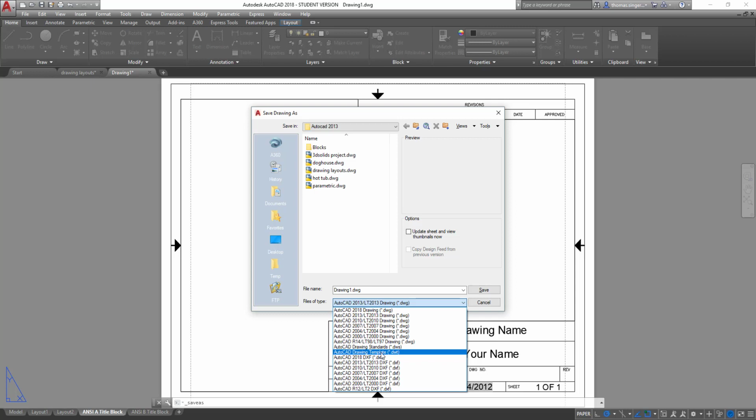So you can create a title block as a template that you can then bring in and apply on top of a layout. That way you're controlling exactly how your title block acts and reacts on the paper. You're not scaling the title block to try to fit the paper. Everything is based on the layout and the scale of the paper.